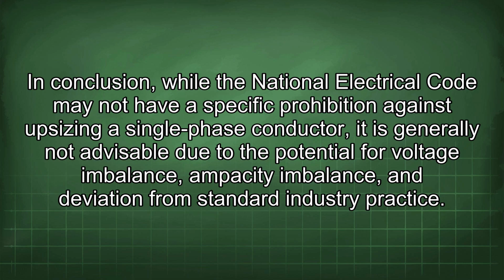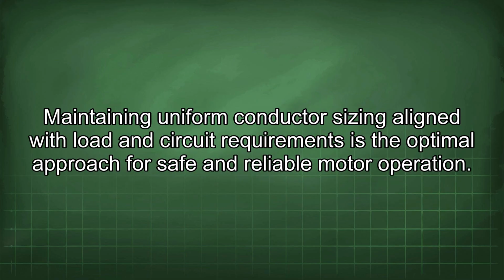In conclusion, while the National Electrical Code may not have a specific prohibition against upsizing a single-phase conductor, it is generally not advisable due to the potential for voltage imbalance, ampacity imbalance, and deviation from standard industry practice. Maintaining a uniform conductor sizing aligned with load and circuit requirements is the optimal approach for safe and reliable motor operation.